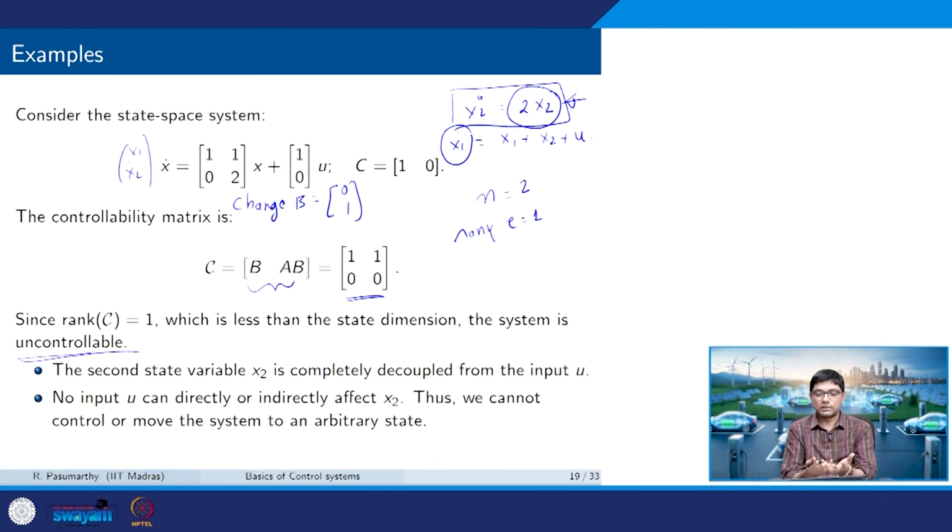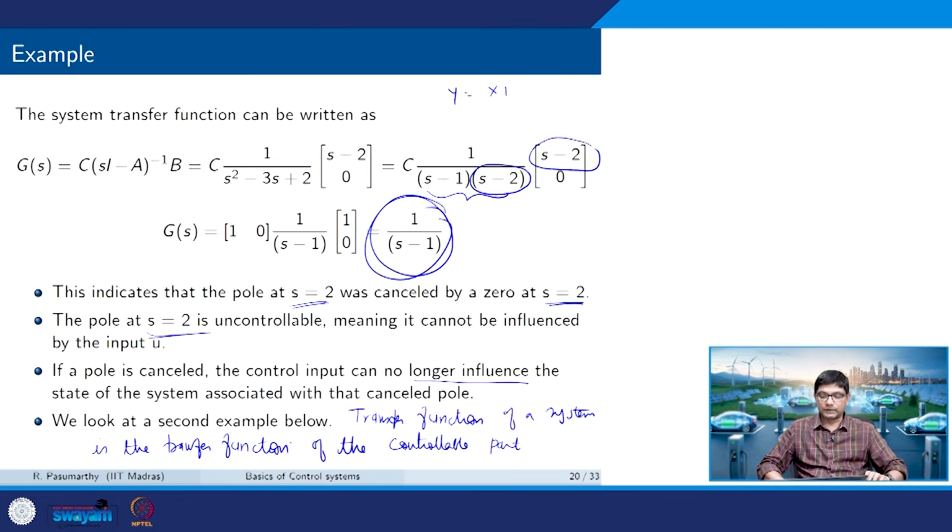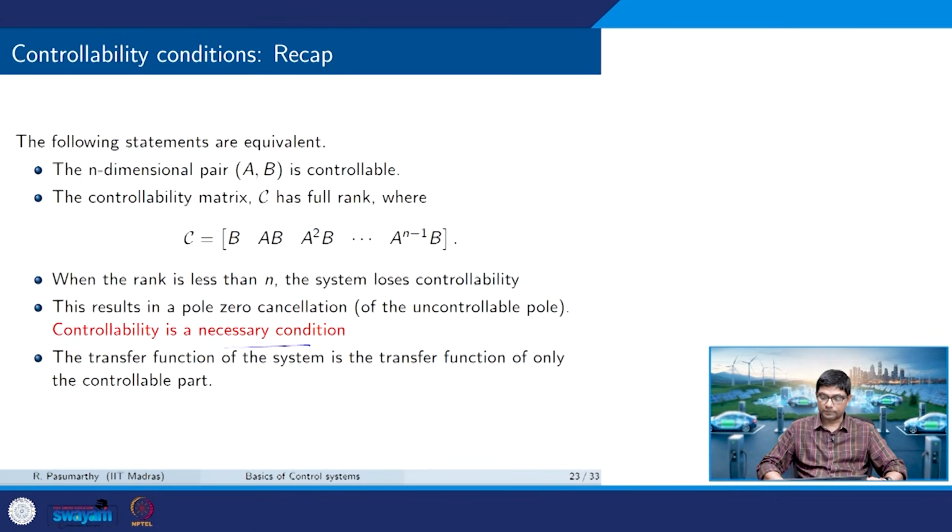Is it not controllable? So ask yourselves, maybe just take pen and paper, just derive the controllability matrix. If the system is controllable, justify for yourself why it is controllable, why it has become controllable now from being originally uncontrollable, or if it is uncontrollable, just also justify why that uncontrollability remains the same, even though I have just flipped the way the input enters into the system.